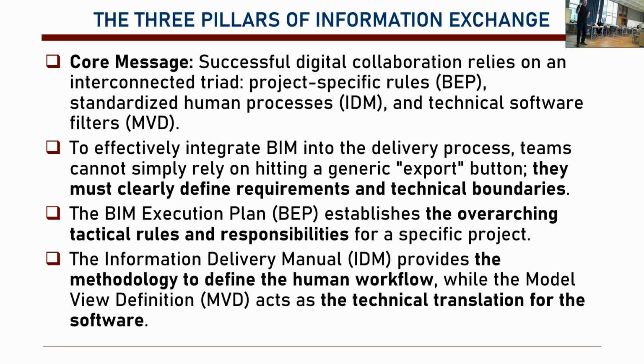In that case, for instance, if you're using Revit and at one stage you need to export the model for the facade consultants, then you define what facade designers need. You create an export filter, and then you export it for them. So what you export works for them. The information delivery manual provides a methodology to define the human workflow.